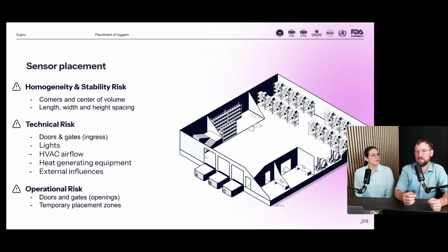So you need to place a sensor at the position where the HVAC air hits your product, and yet again, there are typically several exits of HVAC air, and you need to take a representative number. We also often have heat-generating equipment. We mentioned hydraulic lines before as an example, but it could also be forklift chargers, any type of equipment. We also need to place a sensor where there should be product, but closest to the heat source.